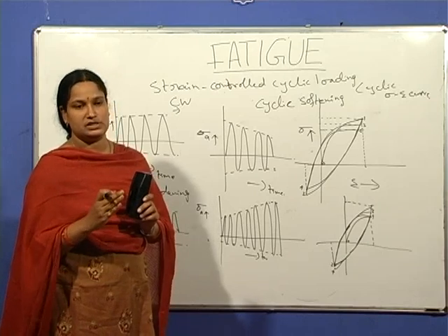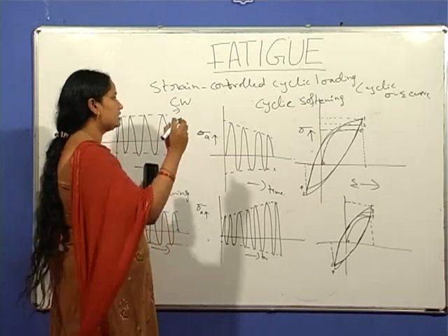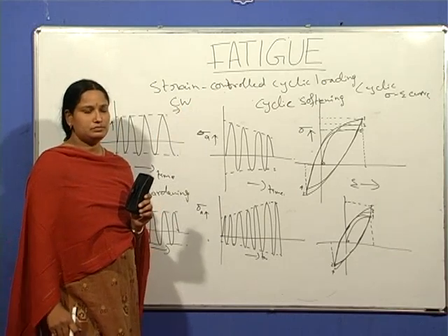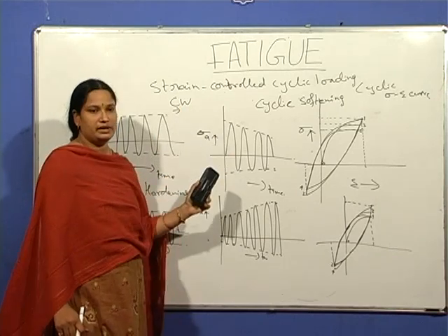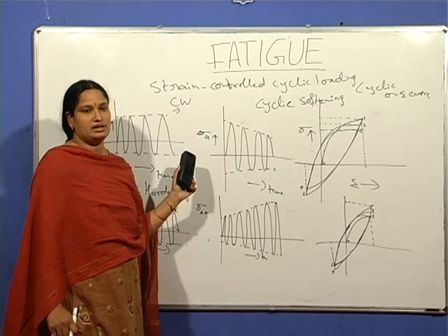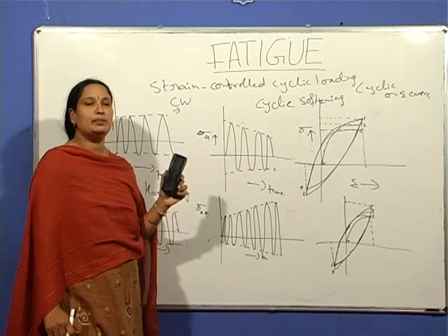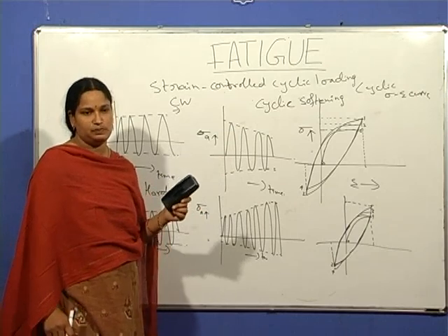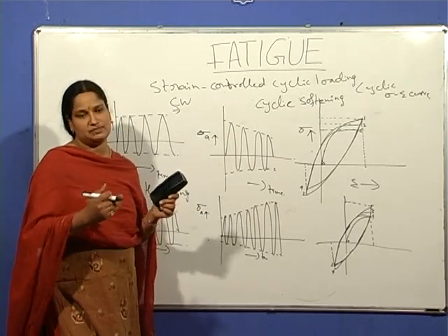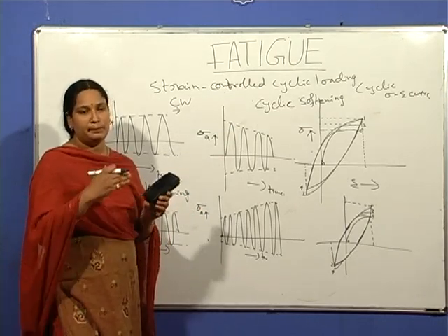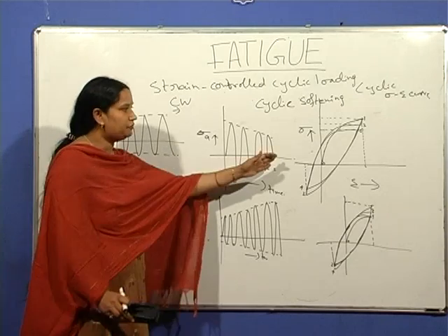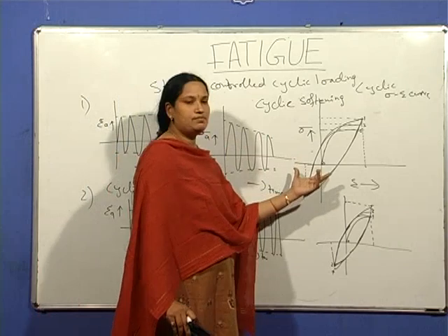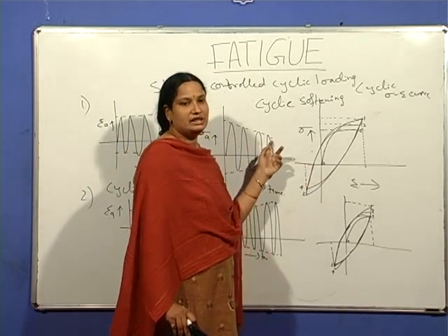The dislocation density is high in a strain hardened or cold worked material. Upon cyclic loading, the dislocations rearrange into a more stable network, or annihilation of dislocations takes place and their number comes down. Thereby the material undergoes softening, that means the stress amplitude needed to maintain the same strain range decreases during cyclic loading.